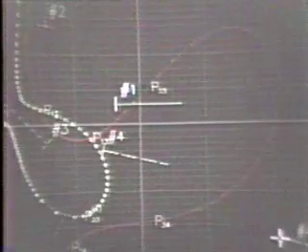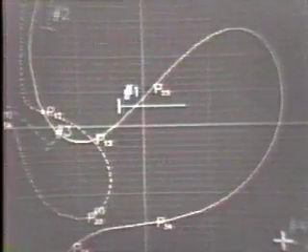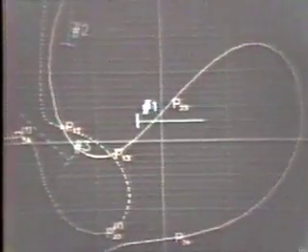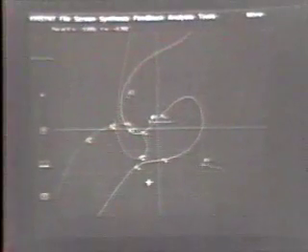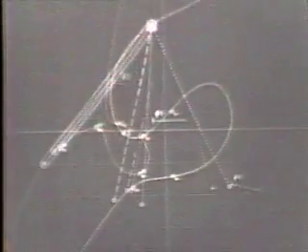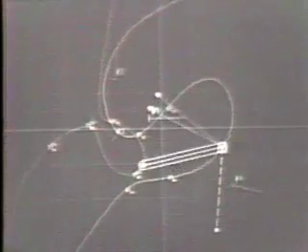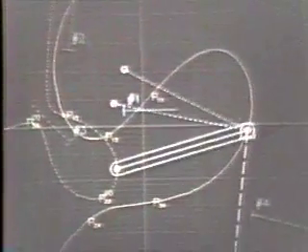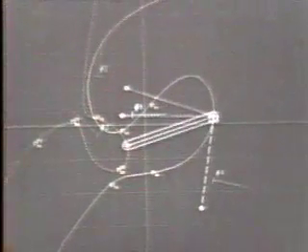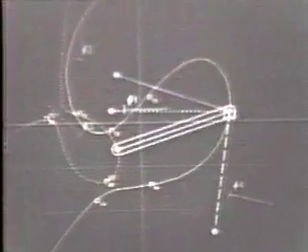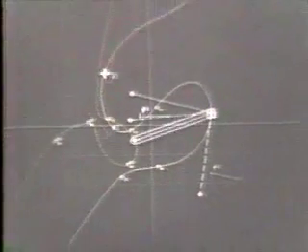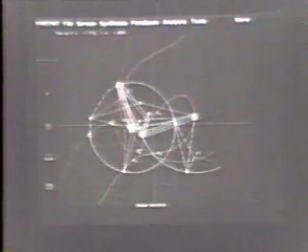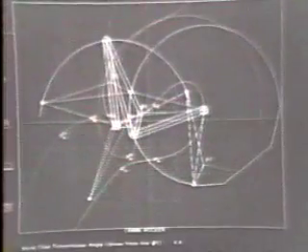Changing the slope or the position of one of those design positions slightly has a tremendous influence on the shape of the Burmester curves, and sometimes just the slightest variation in a design position will move one of the Burmester curves over into a convenient location that might otherwise be overlooked using conventional techniques. Notice that as the designer scans one pivot along either the circle point or center point locus, the corresponding pivot moves to its location on the other locus.